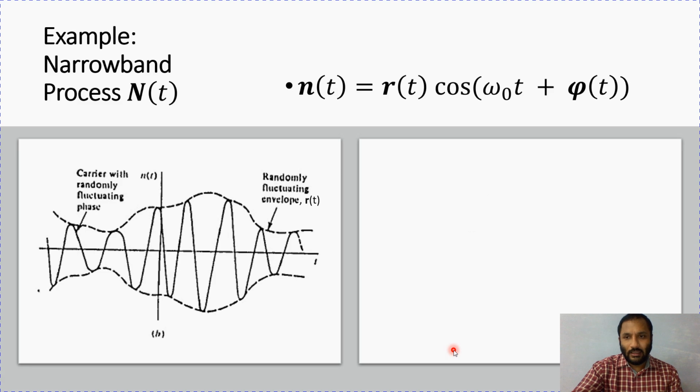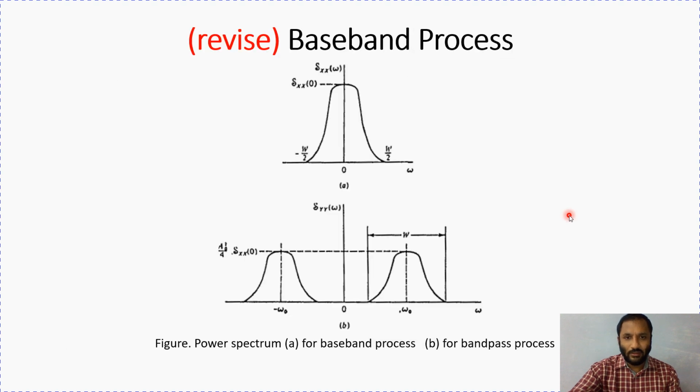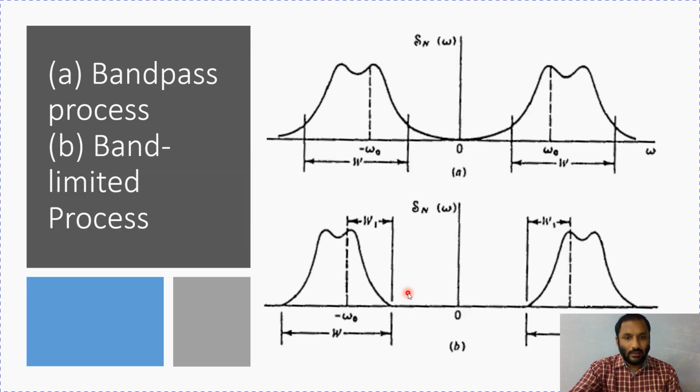The example of this can be seen in the diagram as well. Now look at any of these diagrams of the PSD. You can take this example or the very first example, much clearer. This is the PSD consisting in this bandwidth of W, and with respect to omega equal to omega naught, you can see that the reflection of the right half of this function is exactly equal to this side. It is an even function with respect to omega equal to omega naught. When you have this type of characteristic PSD, then we can simplify the inverse Fourier integral in that fashion.